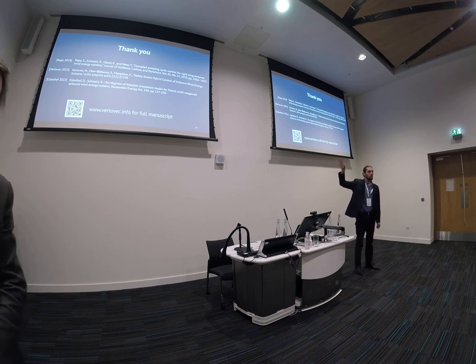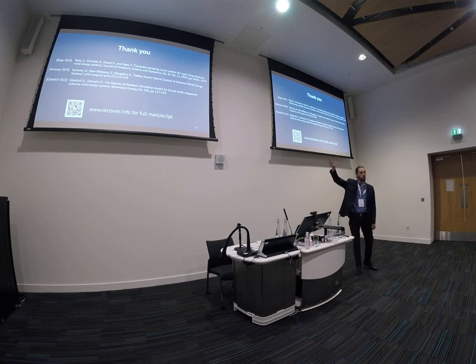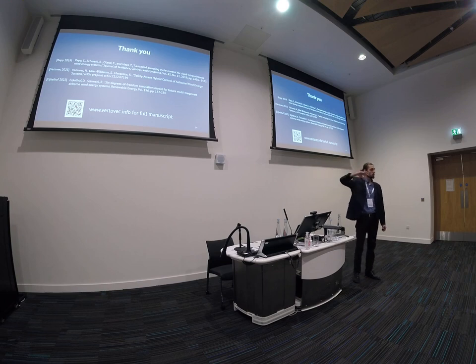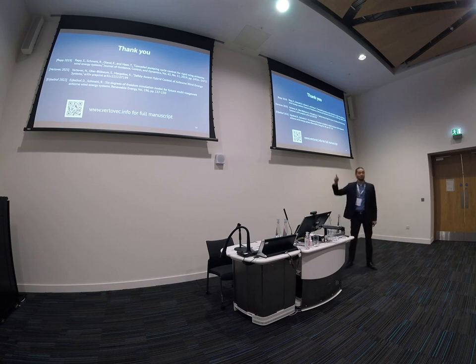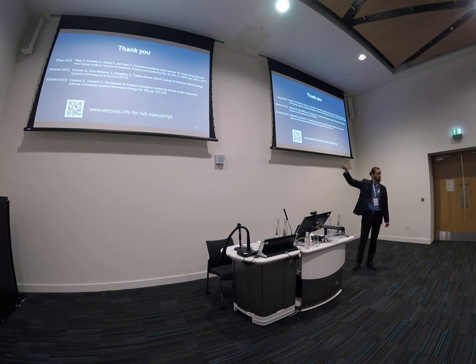Concerning the flight control structure, these were two different types of safety filters that we can see in practice. I think it would be really nice to also design a control barrier function that would work with the flight controller, so that we're not having these problems of a switched system, but that we can use that sort of smooth quadratic program. But there's quite a lot of challenges that go with it. It has a higher relative degree, so we need to use higher-order control barrier functions. The flight control dynamics aren't necessarily control-affine, so that creates its own problems. So there's quite a lot of room there for improvement. I know that you're working at Kitemill, and I wouldn't recommend using exactly this control barrier function just yet, but more the paradigm of using safety filters, if that makes sense.